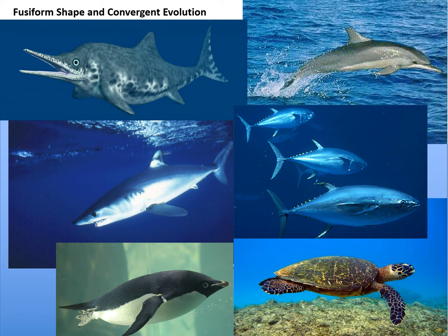This same principle, it doesn't matter whether it's water or air. All that matters is the Reynolds number. If the Reynolds number is high, then there will be very, very strong selection for this fusiform shape. And what that does is reduce the pressure drag, so that the only real drag these animals are worried about or have to overcome then is the skin drag, that tangential surface drag.